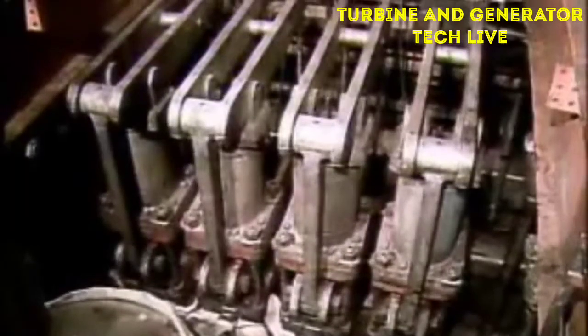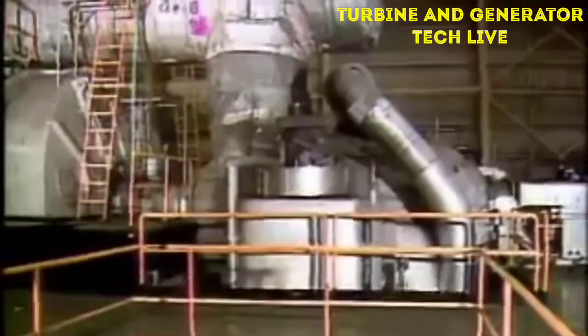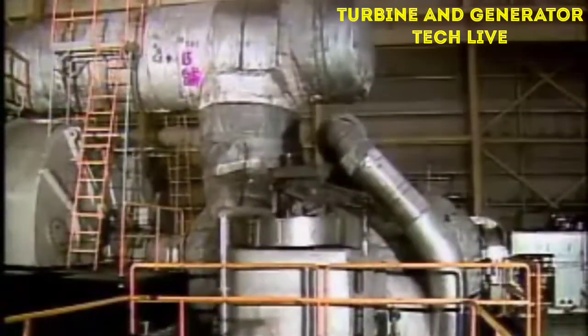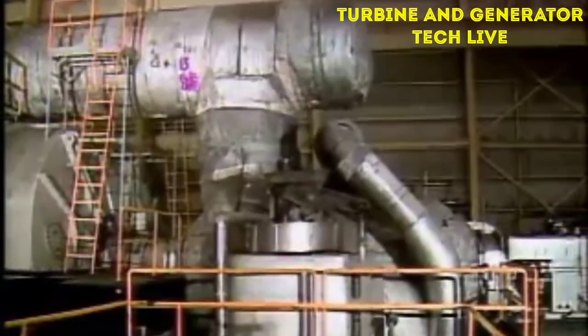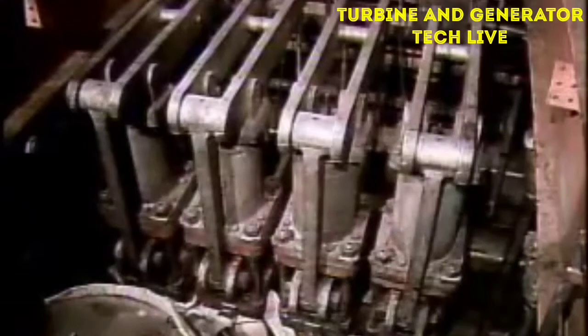As you know, turbine speed is regulated by the control valves. If turbine speed increases during normal operation, how do you think the control valves will respond? If turbine speed increases, the turbine control valves will compensate by closing. To prevent overspeeding, the intercept valves close, cutting off steam from the reheater.